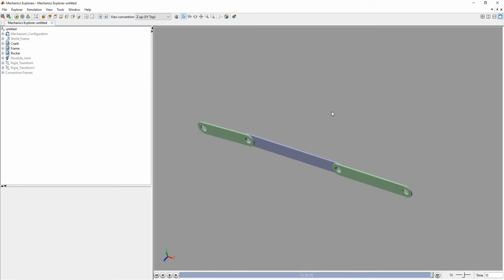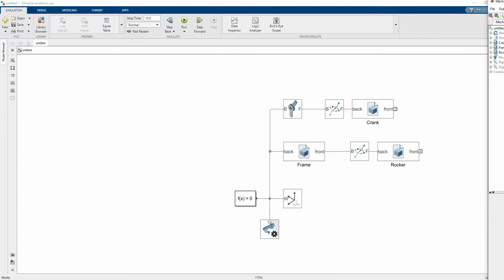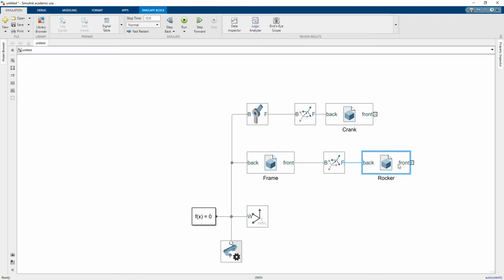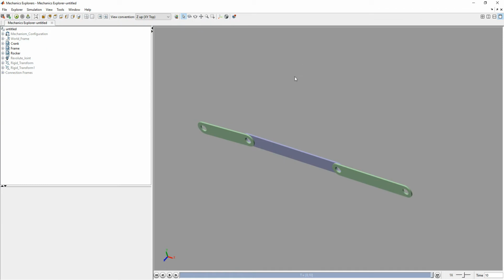I froze then. I kind of thought, why is that not rotating? Go back to the model. I bet you some of you have been sat there going, you silly sod, you've missed a bit. I have missed a bit. So the revolve doesn't know it needs to revolve. It just says, well, yeah, I'm doing what you told me to. It's the worst thing with MATLAB. It won't tell you if you're doing something daft like that. So I can be daft, as you may have realised.